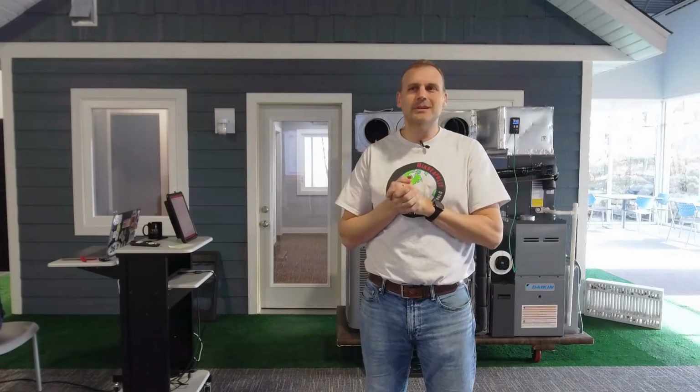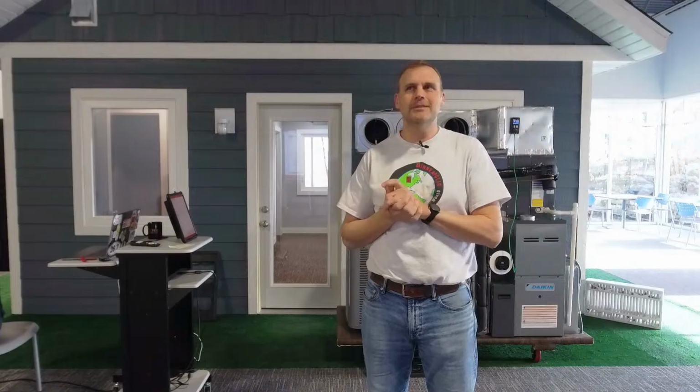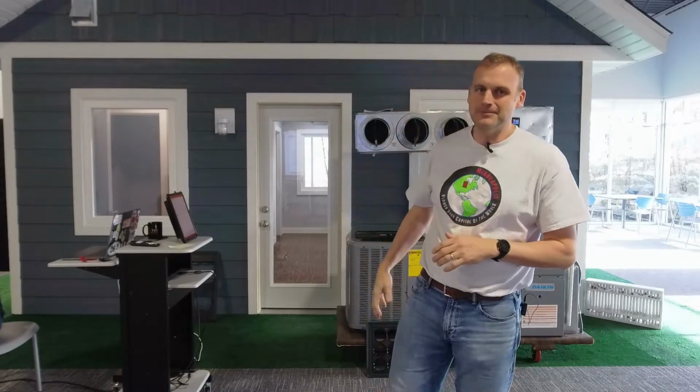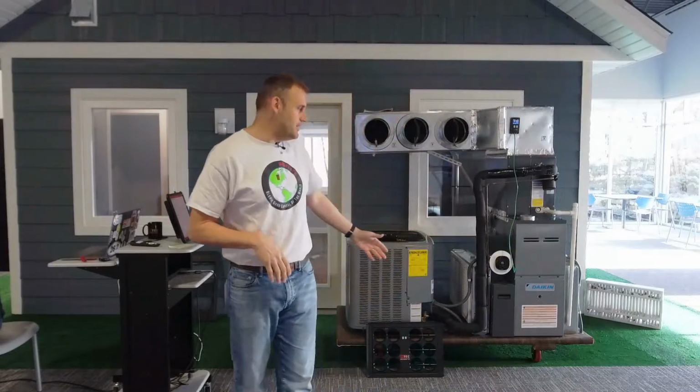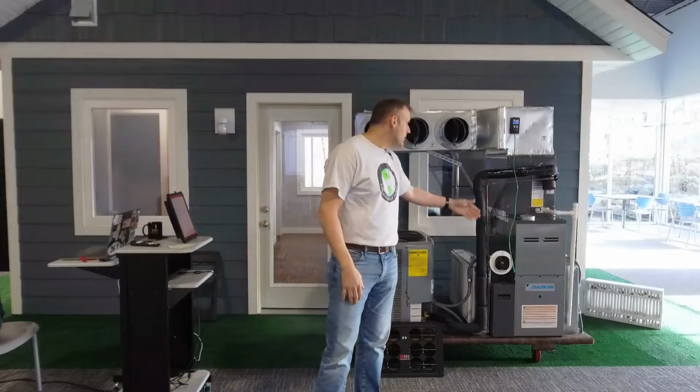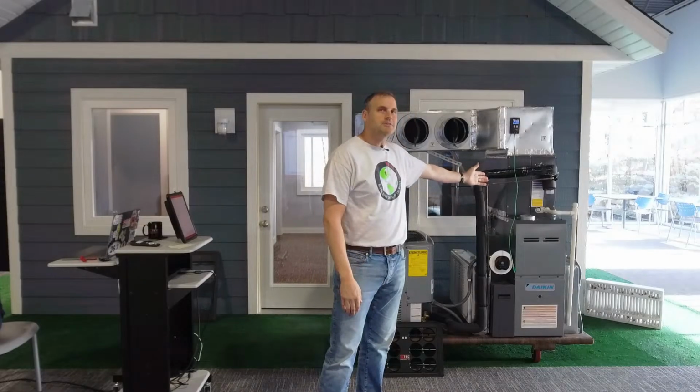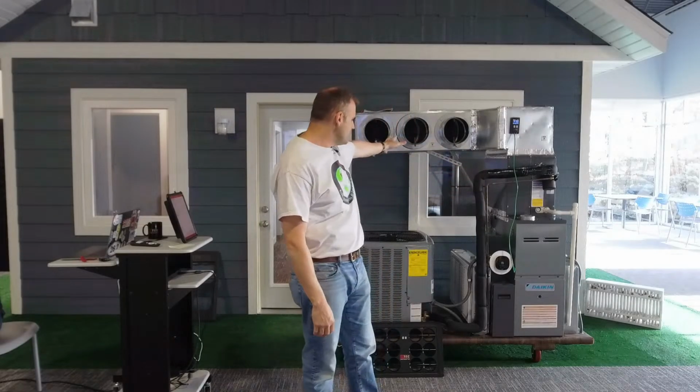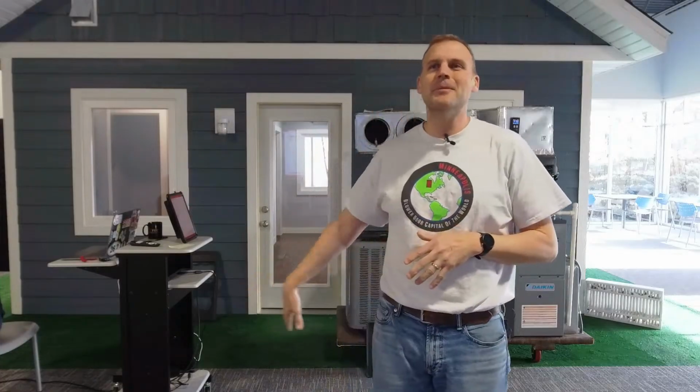Quickly, let's talk about the purpose of the tool a little bit more and what we are going to do with it. Total system airflow. I want to measure total system airflow, and today I'm going to do it on this lab unit. Right now I have a furnace with an evaporator coil right on top, hooked to a very miniature duct system. I've got a condenser, but I'm not going to be running it today because I don't have 230-volt power to it.